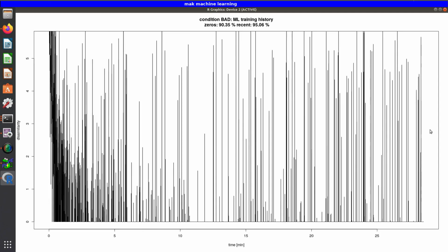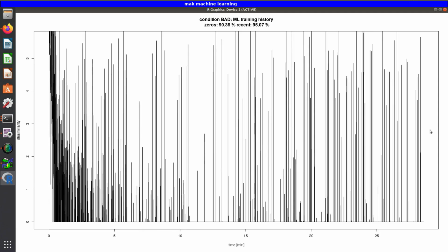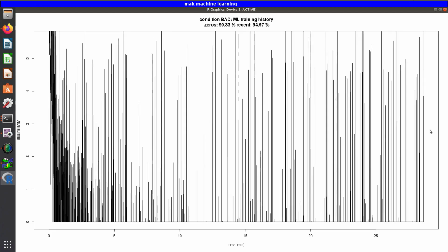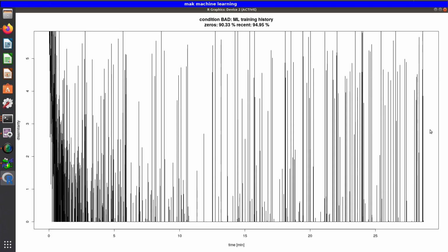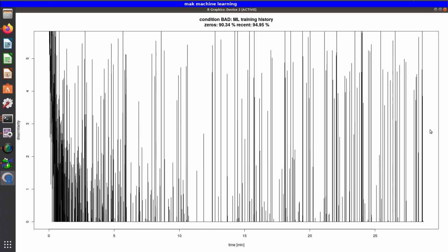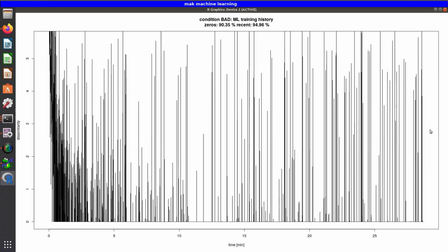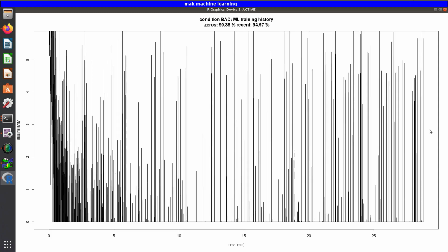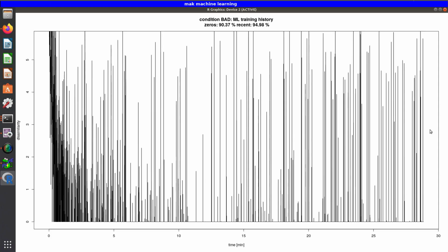If in a production process a condition lasts only for 10 seconds, for example, then we would only train for 10 seconds. However, the condition must be reproducible, so we can repeat the training in order to capture all the admissible variability within this condition.